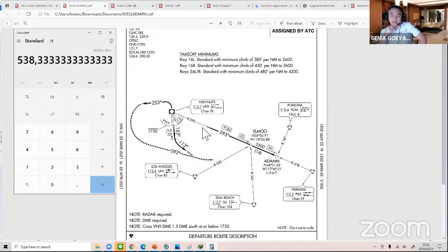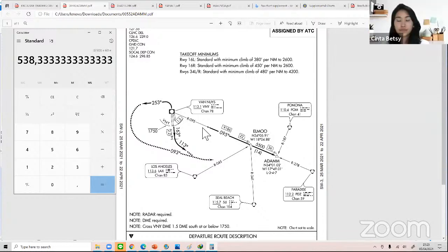Yeah, I just cancel IFR. Duchess 664 Whiskey Yankee, we have an engine problem. We're declaring an emergency, canceling IFR. We fly back to Van Nuys, left traffic, runway 16 right, and coming back, right? Right, because you cannot comply with this anyway. You're not going to fly it.